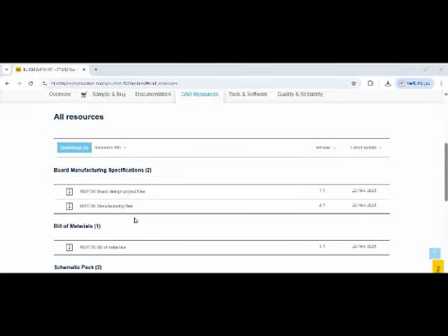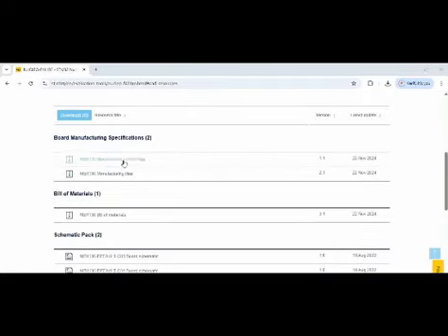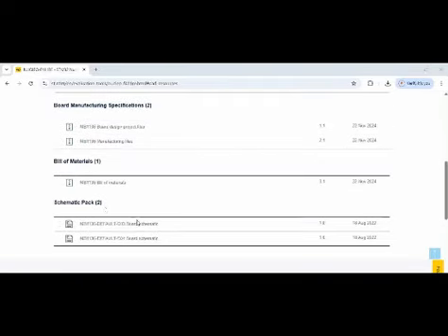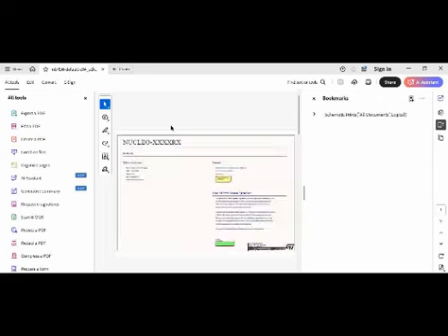Okay, so now you can scroll down, you can see here there are project design files, manufacturing files, and then you also have schematic. Okay, in the schematic you can see here there is C03 as well as C04. MB1136 is internal naming to the ST micro, so that's how they name. MB might refer to motherboard, and C04 version or C03, which one you have to take depends on the board you have purchased. So on the board you will have numbering whether it is C03 or C04. We have C04, so we are clicking on C04, and this is the schematic.